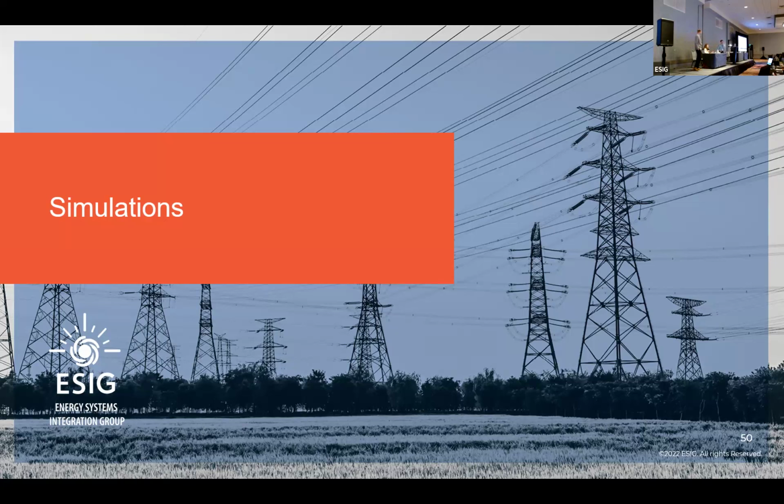But on the other hand, we're now talking about things like augmentation of battery storage, where say Tesla is augmenting on the AC side, and they are doing it basically on a continuous basis. They are adding inverters to the battery and keeping the output at the same megawatt level as the generation interconnection agreement.